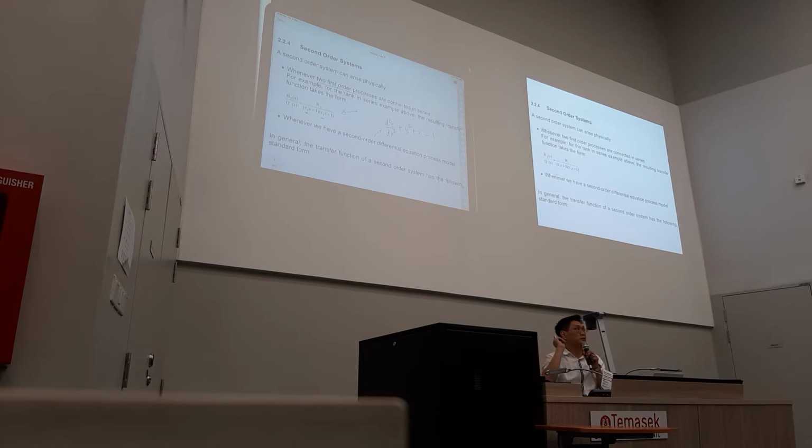This type of differential equation in chemical industry or chemical engineering, later when you come to reactions or some calculations, you will see these types of second order differential equation. And this can also use Laplace transform to solve. But we will not learn how to solve this one for this module itself. But just bear in mind, for a second order system, the first one looks like this format, the second one looks like this format, where we call it the differential equation process model. So in general, the transfer function of a second order has the following form.